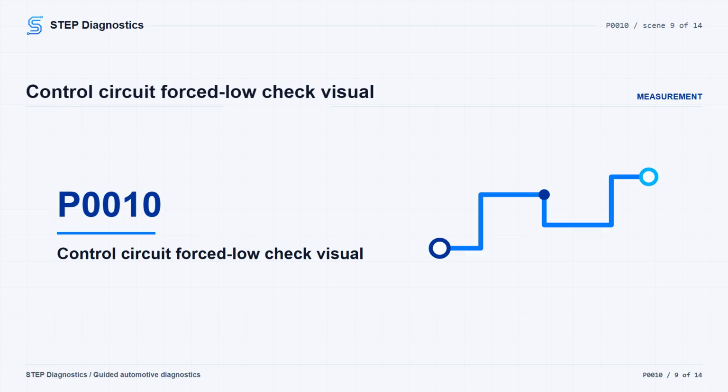If the test lamp did not turn on during that control circuit check, turn the ignition off, remove the lamp, and connect a 3A fused jumper wire between control circuit terminal 2/B and ground. Start the engine and command the intake/single camshaft position actuator position from 0 to 20 degrees and back to 0 degrees. The scan tool should show the intake/single camshaft position actuator control circuit low test status as malfunction. That confirms the ECM can recognize the forced low condition.